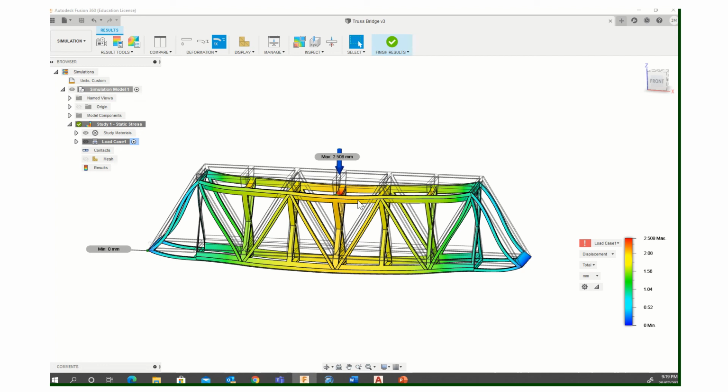If the bridge is supposed to have a safety factor of 2 and your bridge is too strong and you use too much material, that means you are wasting resources. So maybe if your safety factor is above 5, it's going to be a waste of materials and design. So you have to be at a safety factor of 2, maximum 4. Right.